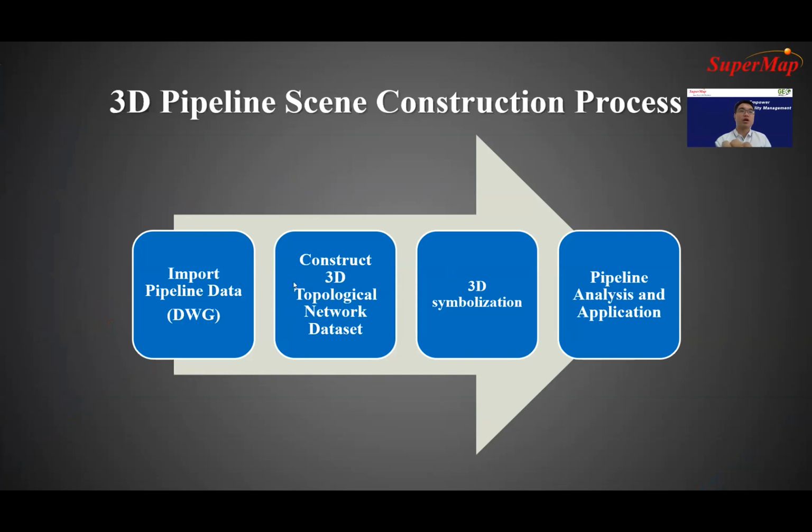You can see in this chart we have several steps. The first step, we have to input the pipeline data. Some data can be from Autodesk. After that, we input it into the SuperMap platform. Then we can do some topology checking, and we can construct the 3D topological network. Then we do the 3D symbolization. We add some symbols, add some marker layers, and then we can build the 3D scenes. In the last step, we can use our new scenes to do some 3D analysis and some applications. And then we can also integrate with our own business system.